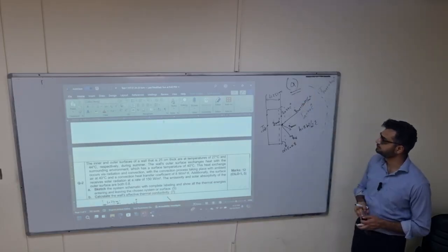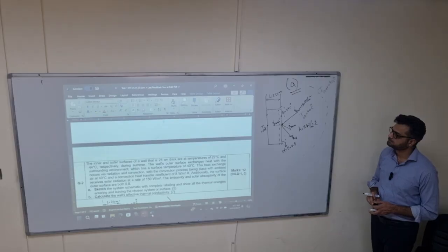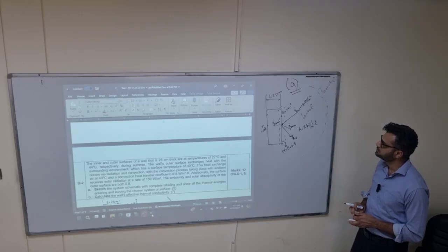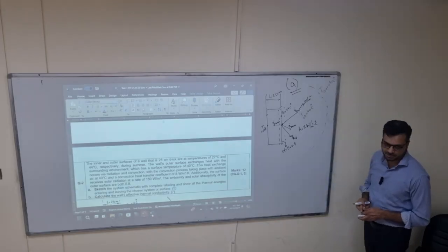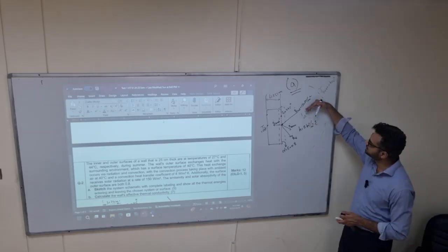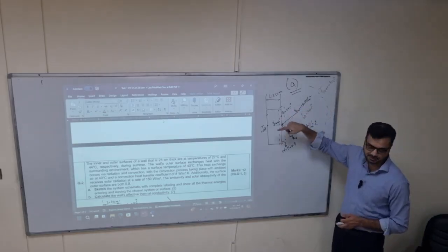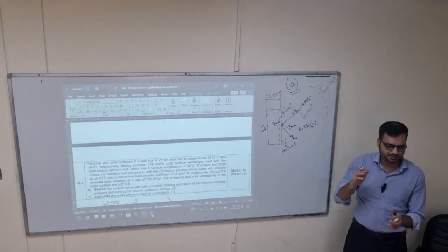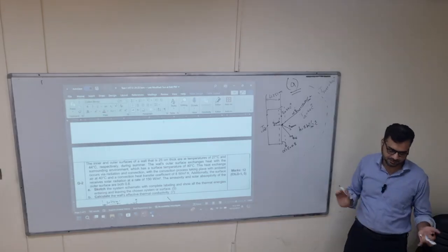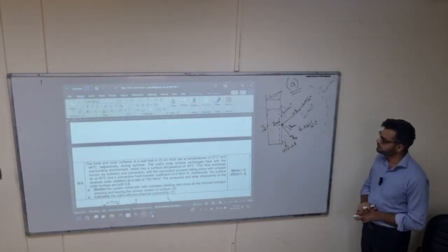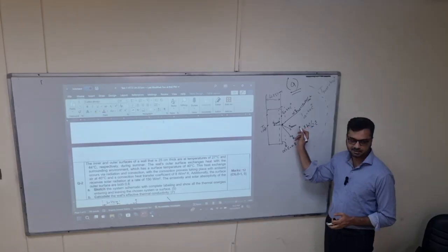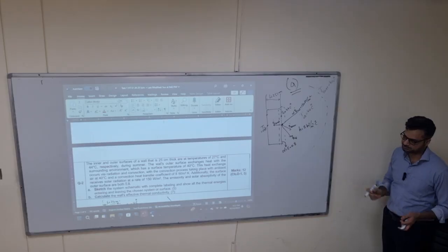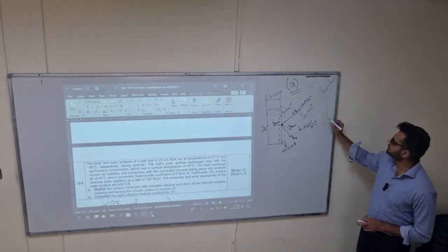Should we add another arrow for the reflected Q, because the emissivity is 0.8? Okay, if you add it, good. But here I'm saying this Q energy is incident, but how much is absorbed is actually, yes, you're right, then we should write it like this. But if you are not writing it here, but you are writing it in the equation, it's fine. Otherwise, if you show Q reflected also, 0.2, that is also okay. Not required, but it's fine. So this was part A, 5 marks.